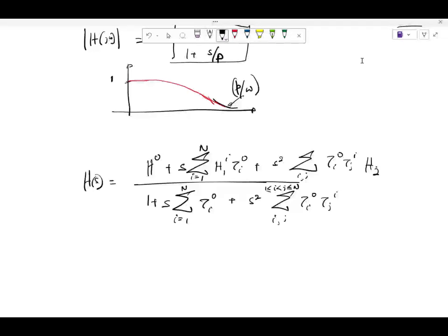Was this H2J or H2I? What was it on the subscript, superscript? IJ, right? So an easy way to remember these transfer constants is that they are computed under the condition that whatever you have on the superscript is shorted, I mean, set to infinity.